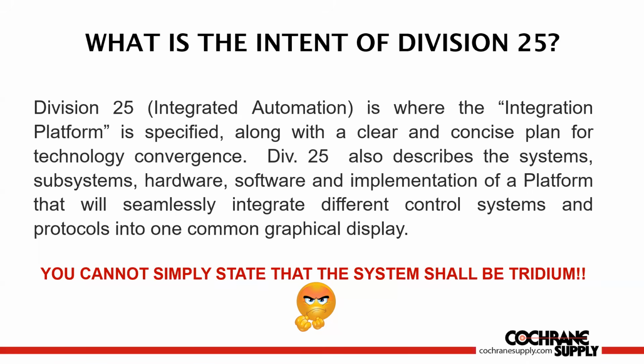So in other words, when you're specifying controllers, when you're specifying these other things, there's a ton of systems integrators in every market who are Niagara certified, right? So someone from an equipment manufacturer may say, hey, we've got Tridium's Niagara, and we've got BACnet, we're open. Well, there's only one office in that marketplace that can purchase that software or that hardware and program it and maintain it.